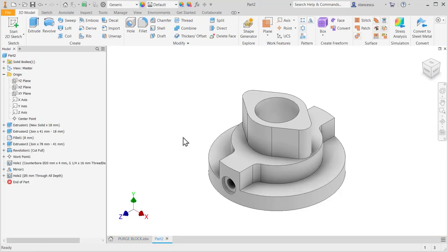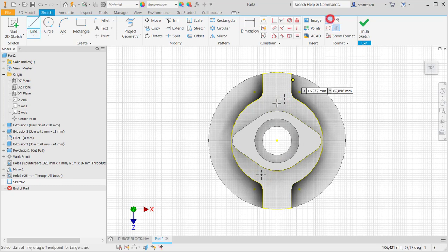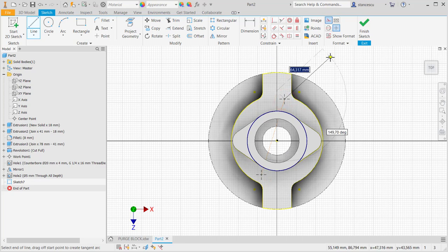Okay, I select the face, I place 2 points, 1, 2, I connect them with the construction line, I disable construction, coincident this midpoint, where is it?